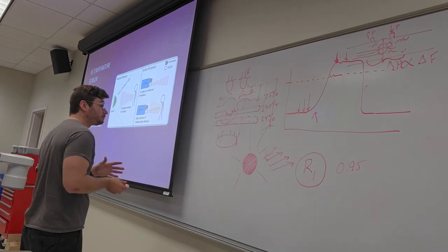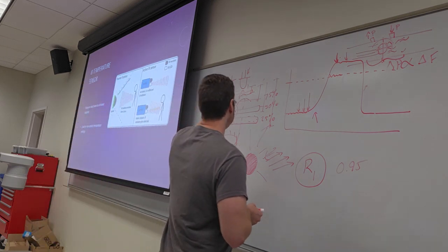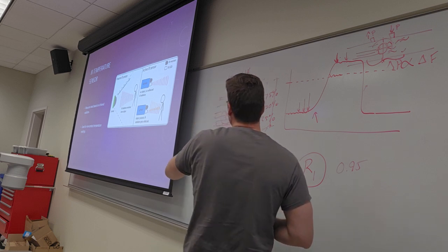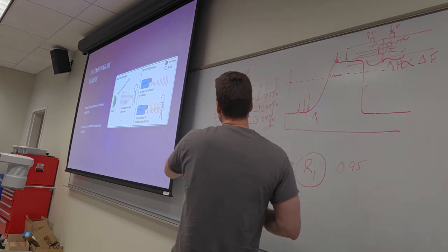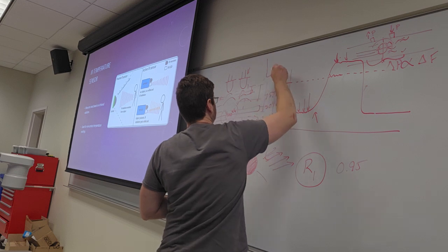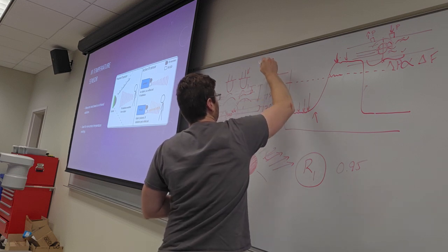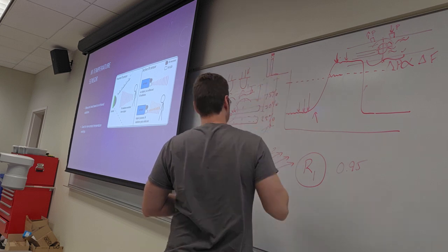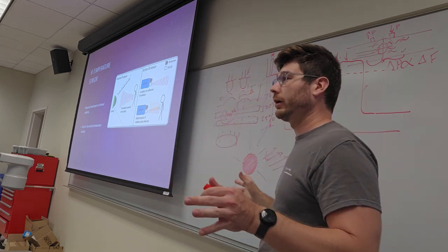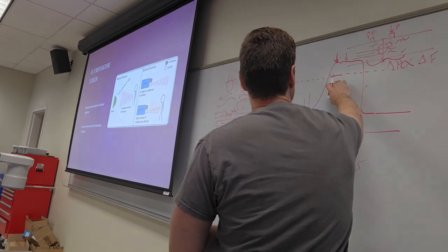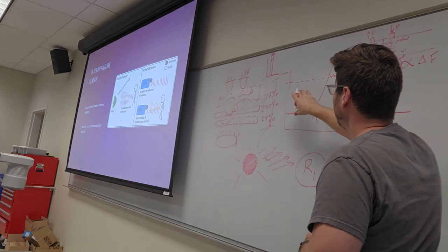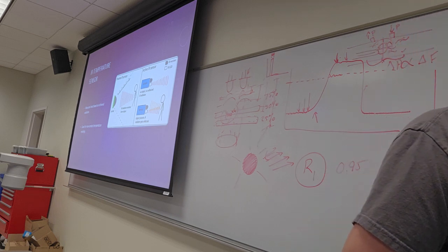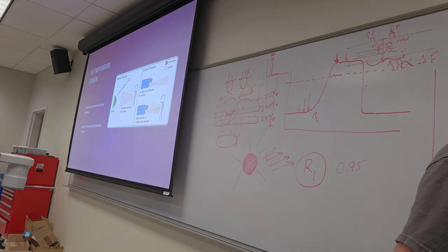All right, and the other one, like I said, we intentionally create IR and see how much IR we receive. The reason we do this time gating technique, where we pulse it and only look during that pulse, is because things are giving off IR all the time. This signal that I was talking about here, if we didn't pulse it, looks like this. Let me know if you guys can't see this.